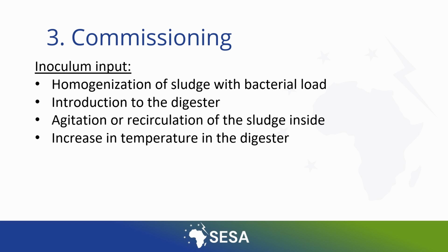Once the sludge has been introduced, it is necessary to homogenize it inside the reactor, as well as adjust its temperature to between 35 and 40 degrees Celsius. In this way, the degradation of organic matter will begin and the anaerobic process will start to take place.